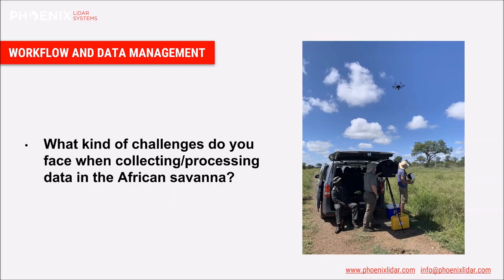Especially because we now have beyond visual line of sight permission, but we did not when we first worked. So there are times we actually had to fly from a moving vehicle, potentially down up terrain, land the drone somewhere else, restart it. So now it has a new 0 point, but the flight software assumed the same altitude, which means you potentially run the risk of running into terrain because there are all these different changes in altitude on some things, but not others. So it was super useful to have the LiDAR unit and Spatial Explorer to add a level of confidence that we're actually at the right altitudes and stuff like that. So yeah, the downlink is really useful in many ways.